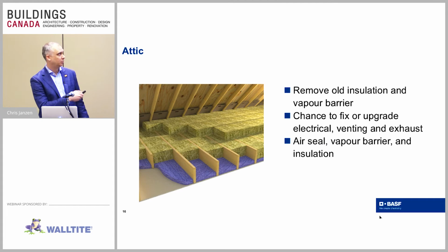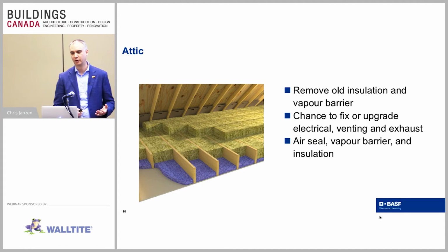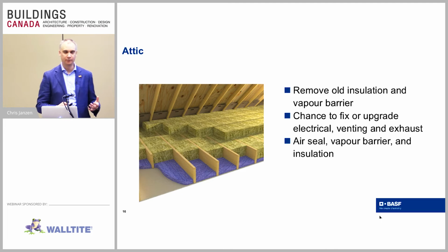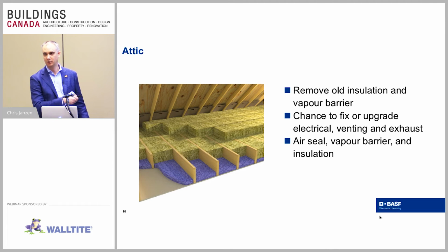They would spray typically about 2 inches of foam directly onto the drywall. Again, that gives you your vapor barrier, it gives you the air sealing properties, and it gives you about an R12 insulation. And then, to be cost effective, because you already have your air seal, you can go back with either batts or blown-in cellulose on top of it to bring it up to your R50 or R60 requirements.